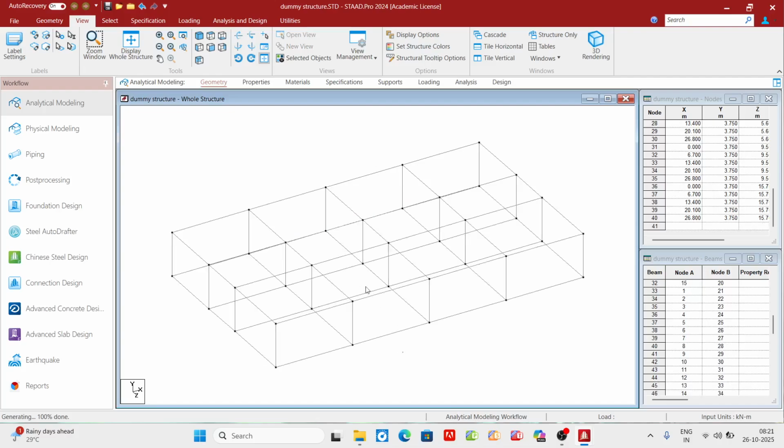And now another thing you have to see is this distance. You can see this should be 3.75, because again I have just told you that the ground floor is this one and the first floor is this one. Okay, follow my cursor. This is the first floor and this is the ground floor. So the distance between these two should be 3.75 because we have applied it in translational repeat.